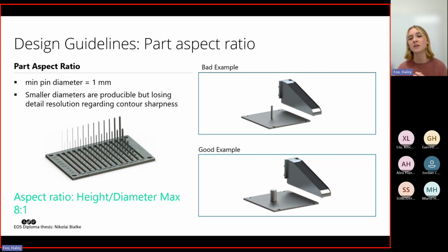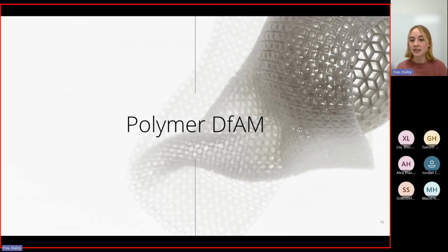It's definitely encouraged because we do have different blade types on our recoater that recoat a soft layer of powder. They use a brush instead of a steel blade. So this isn't to discourage you from doing these intricate small lines, but just so you know that it's also sometimes a design consideration. And that's it for metals.